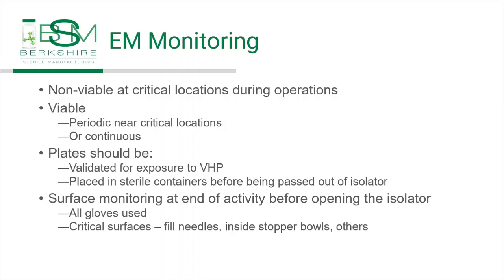Surface monitoring needs to be conducted at the end of the activity before opening the isolator. That's all gloves, critical surfaces such as fill needles, inside stopper bowls, and other places that you determine are critical. Glove integrity tests must be performed.